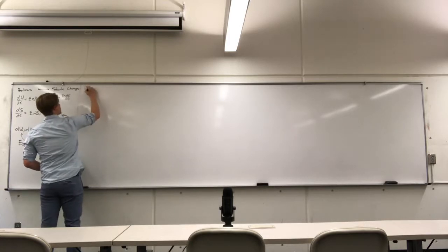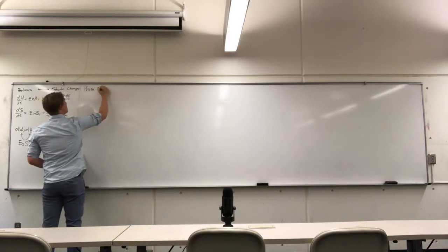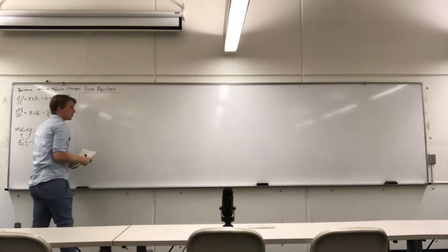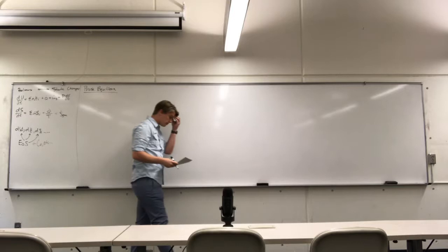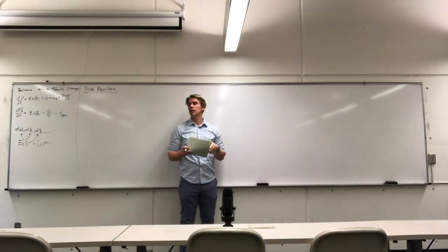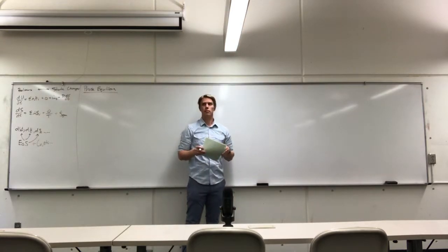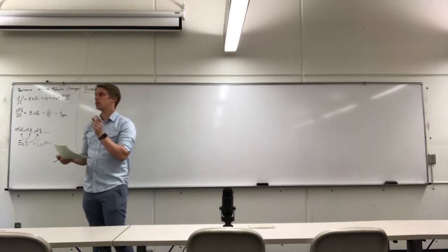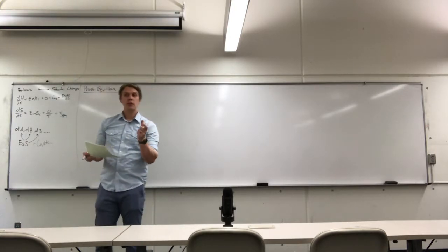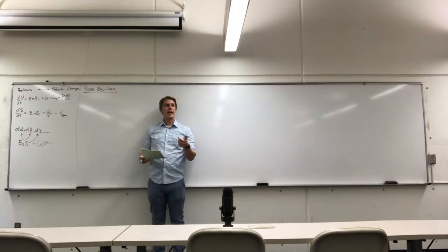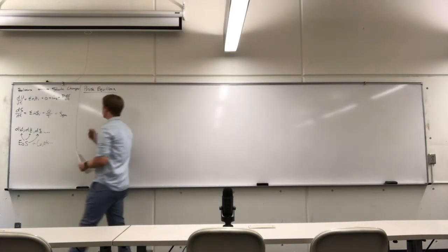This is where we'll be spending most of our time. Phase equilibria. Now, what we're talking about here is if I have two fluids in contact, how do I know that they're at equilibrium? Because if I know that they're at equilibrium, then I can read off specific properties associated with it. Most specifically, as chemical engineers, we care about the composition. So if I have a multi-component, multi-phase mixture, right, a flash calculation is a classic example.